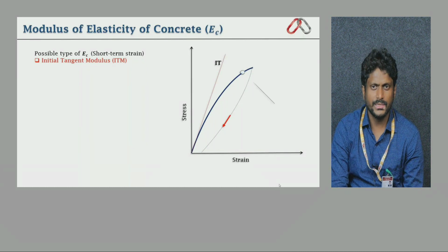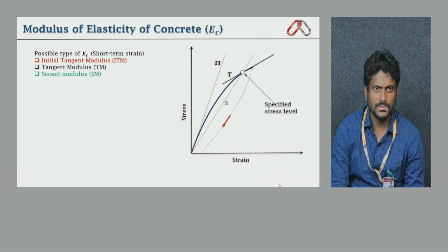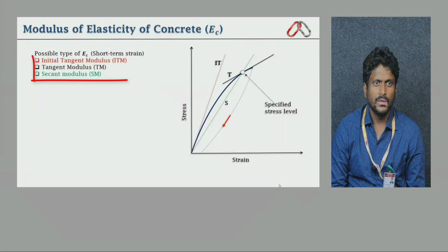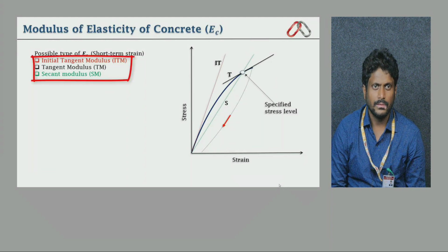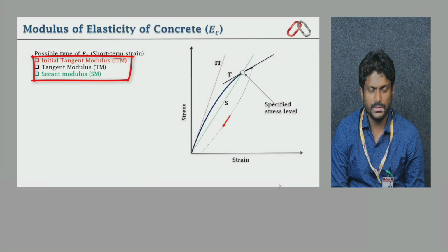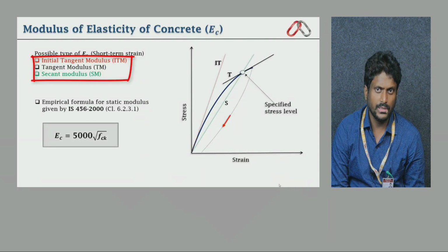So that is tangent, because if you look at the secant modulus, how it is touching the tangent. So that is the secant modulus and the tangent modulus, where it is touching. That meeting point is very important to find your Ec, the modulus of elasticity for that concrete. Why? Because when we are not able to get a straight linear line, when we are getting a curved line, for locating that we need some idealization.